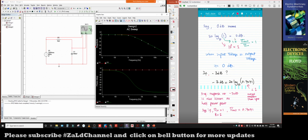So 0 decibel means output and input are the same, meaning that the input voltage will be the same as the output voltage. As you can see the red lines here, the red signal, this one is the signal for 0 decibel. All right. So there is no change in terms of output and input.